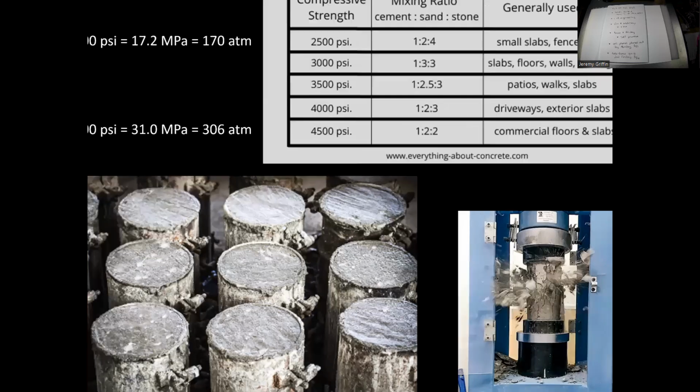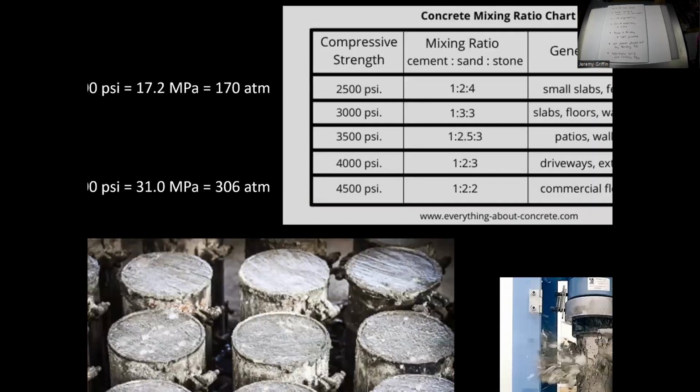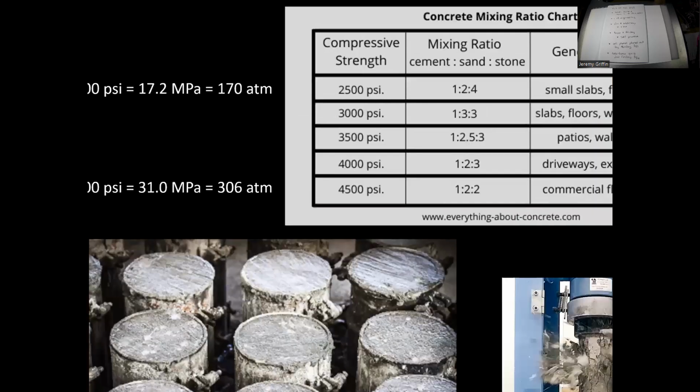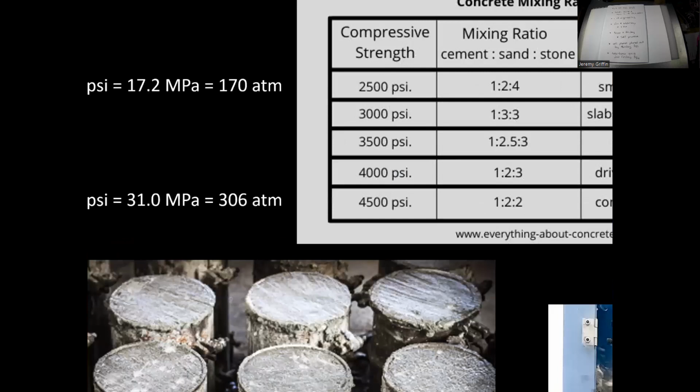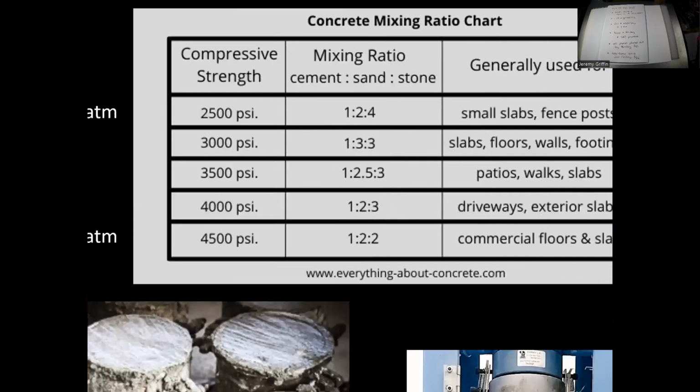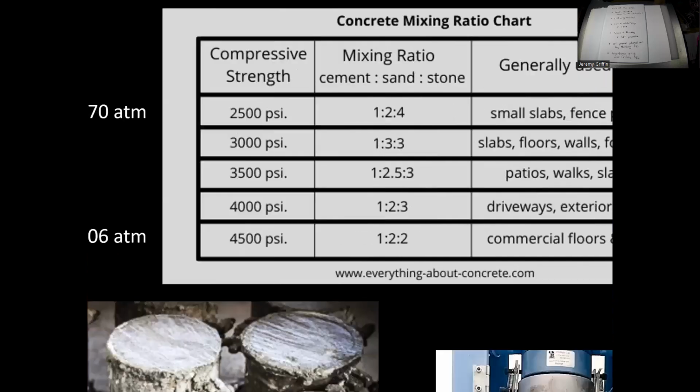So what is the strength of concrete? Now, one thing to know about strength of concrete is that it specifically has a compressive strength, but it doesn't really have any tensile strength. So you can never design a structure where you have concrete acting under some kind of tension force, because it'll just pop apart and it's no good. But compressive wise, it can carry, well, it depends how you mix it. So I got this table of values. Now this is all the concrete you can have, but this is a pretty general table.